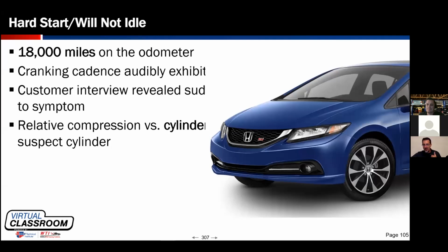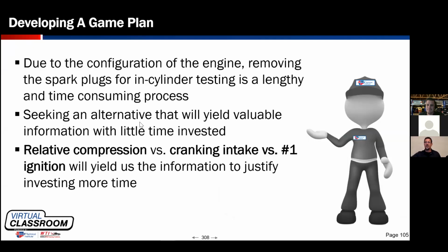So he called me. We established a rapport, right? I'm the guy that works on his car. He said, I don't know what to do. So we had it towed in, and I hear a cranking cadence that exhibits one cylinder that's not quite like the rest. So I decided I'm going to do an RC test. I struggle to get the car inside. It barely runs, I mean barely runs, but I got it in. Now, again, I can't get to anything very easily, so it's even more important for me to establish which direction I'm headed in before I take anything apart.